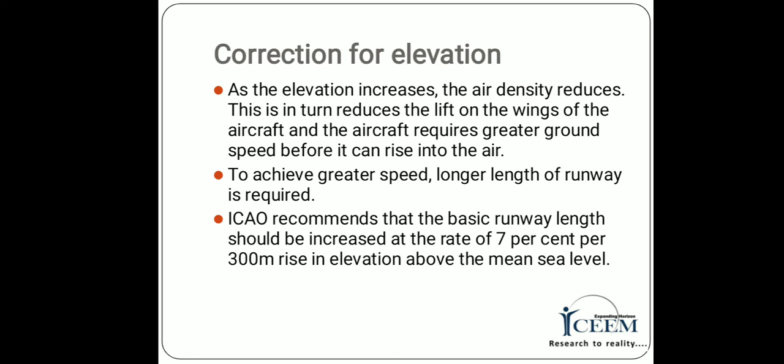Next is correction for elevation. As the elevation increases, the air density reduces. This in turn reduces the lift on the wings of the aircraft, and the aircraft requires greater ground speed before it can rise into the air.